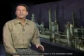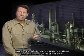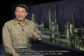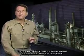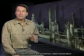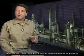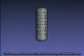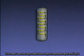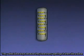At the heart of a distillation system is the distillation tower. Basically, a distillation tower is a series of distillation processes, or stills, stacked on top of each other. The process of distillation is sometimes referred to as fractional distillation, or fractionation, and distillation towers are sometimes called fractionators. Fractionation is distillation that occurs at different levels in a tower. This is a simplified illustration of the inside of one type of distillation tower. This tower uses trays called sieve trays to separate vapors and liquid. The trays are spaced throughout the tower. They're called sieve trays because they have many openings in them, like a sieve.